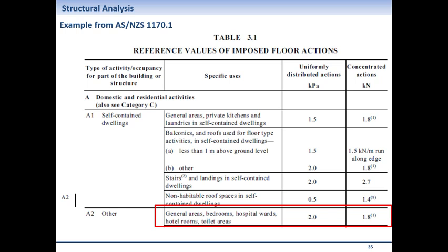So, as you can see, this is talking about imposed, which is another term interchangeably used for live load. So, speaking of that phone call with another engineer at site, if you say imposed load and he or she says live load, that's okay. They mean the same thing. But if you mix up stress with the strain, or stress with the load, or force with whatever else, they are not interchangeable.